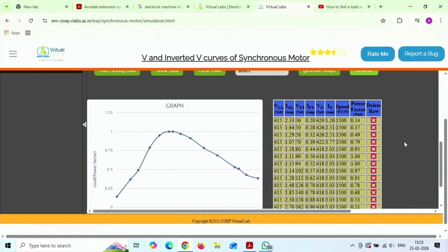Thereby we see, by varying the speed, how the torque-speed characteristic, efficiency and circuit diagram change, and what tests are required to get those equivalent circuit parameters. That experiment is there for induction motors. Alright, so what parameter? Xm, the magnetizing reactance component, we need to find, by using the no load test and the blocked rotor test. Those tests we do for the induction motor case, right? And thereby we calculate the other parameters.